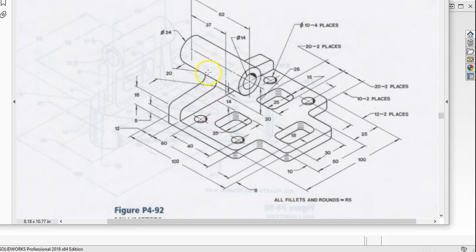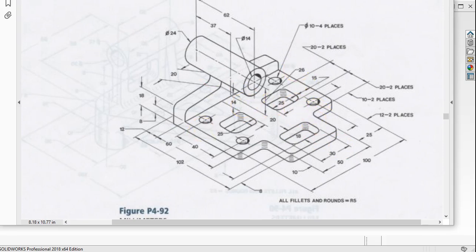All right, so symmetry across the base. Again, from a manufacturing standpoint, if this is casting, well, even that's not structural. There needs to be a rib or something underneath this to help support it as the material is loaded, or whatever that cylinder is doing. We can go ahead and build it as is, and then go with the modifications. So center line is, well, we have symmetry across the front plane.